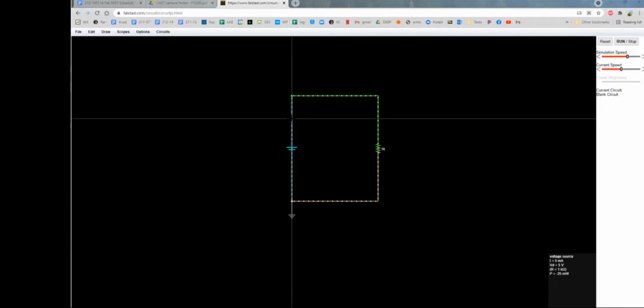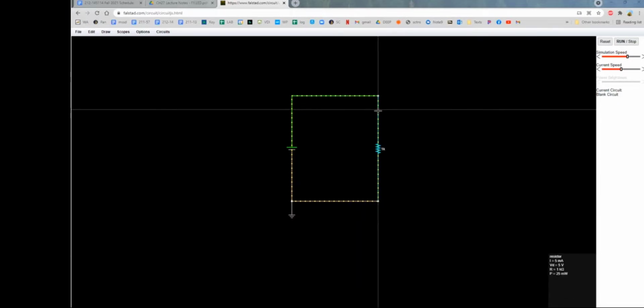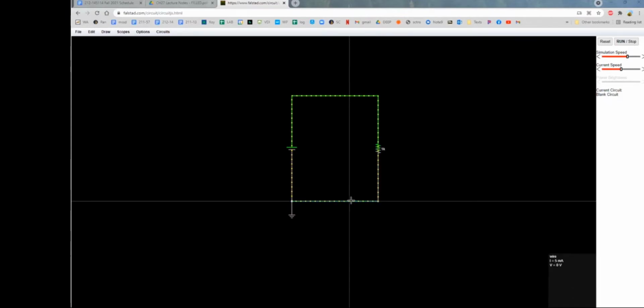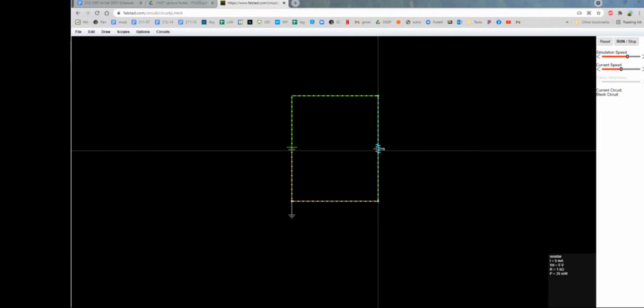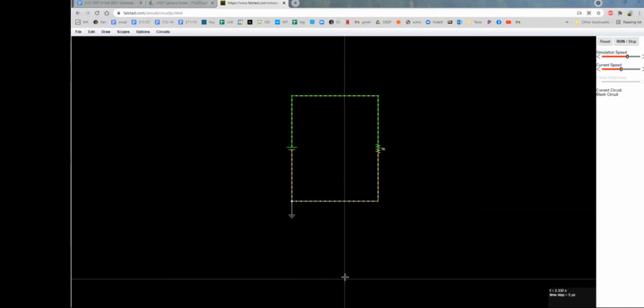which stands for 5 milliamps. And then put it on the top wire, 5 milliamps. Put it on the right wire. Put it on the right wire on top of the resistor, 5 milliamps. So everywhere, no matter where I analyze this circuit, no matter what circuit element or wire I analyze, it's 5 milliamps everywhere, because this is a series circuit.